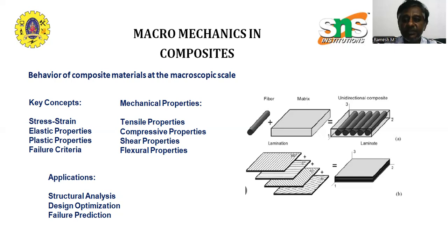You are going to stretch the composite material, so that whatever the tensile strength we can have for the given composite material, whether it can withstand a large amount of strength or not, as well as compressive properties also. We are going to apply compressive load so that the deformation, shrinkage, will be there. Here also the compressive strength we are going to assess.